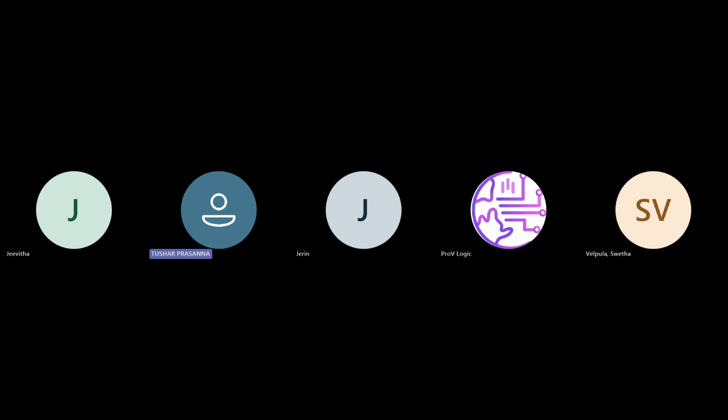These are all non-synthesizable statements. With for loop, we can iterate the inputs, and with repeat, we can do the same, but we can give the value like repeat of 20 for the clock in a test bench. Okay, good.